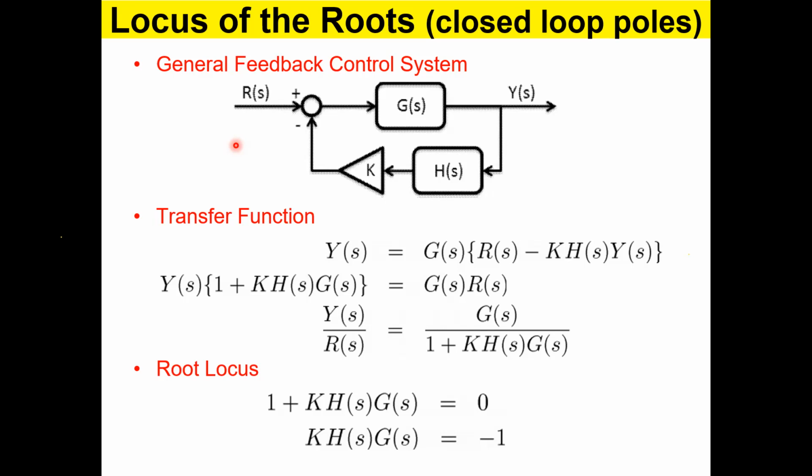So we have already seen that putting a feedback gain over here gives us the leverage to control or dictate the terms in the loop, to make it unstable, even to make it critically damped, oscillatory, rigid body motion, everything, right? So that is what is called controlling a plant. This happened more than half a century ago, right? What we are trying to do today: a person by the name Evans did a lot of good work and put this feedback gain paradigm into a very elegant criterion for designing feedback loops. So we are going to do just that. Now here you can see a plant, a sensor, and a feedback loop.